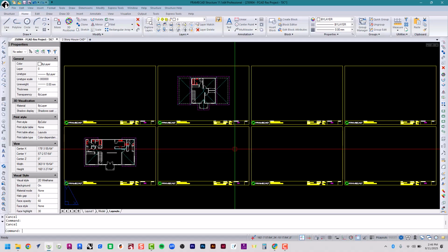Now that we have our blocks strategically placed in our borders, we need to assign reference points to each border so that vertical loads transfer down our structure properly. We do this using reference points, which allow our 2D views to interact with one another. For the reference point system to work properly, there's 4 rules that must apply. Only one reference point within a border, minimum of 2 reference points for each reference number used, only one reference point number for each structure. Each reference point must be placed in a corresponding point within a border to a primary reference point.